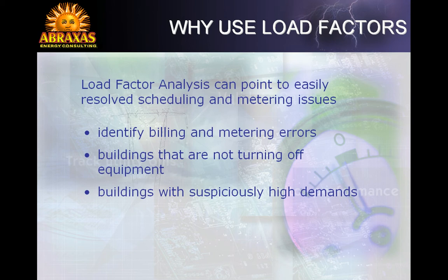You can determine your own rules of thumb for your buildings. However, your range of acceptable load factors will vary based upon building type and climate. Identifying the buildings with unusually high and low load factors relative to the other buildings in the portfolio should be sufficient. In summary, load factor analysis can point to easily resolved scheduling and metering issues. Load factors can be used to identify billing and metering errors, buildings that are not turning off equipment, and buildings with suspiciously high demand.